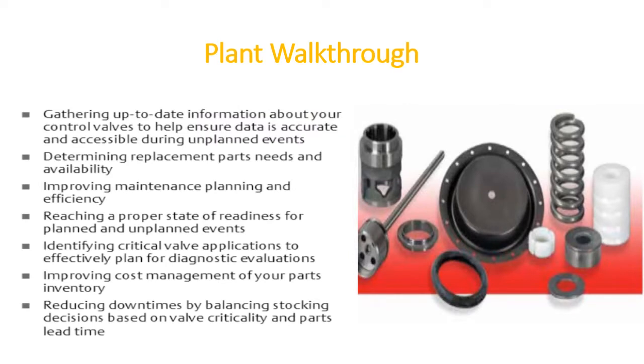So first, if you are just starting the plant, or you want to start doing the spare management from scratch, you should do a plant walkthrough and gather all the data related to the valve. You should make a register.